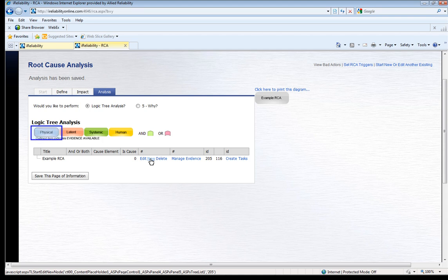The 4 types are: Physical. These are physical conditions of the equipment such as shaft misalignment, etc. Latent. These are behaviors such as attitudes toward precision maintenance or PDM, etc. Systemic. These are circumstances such as degraded machine condition or no performance standards, etc. Human. These are capabilities such as skill deficiencies or lack of motivation.